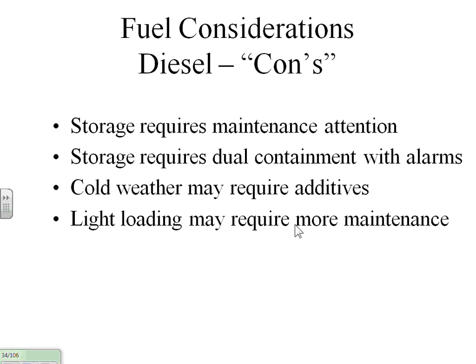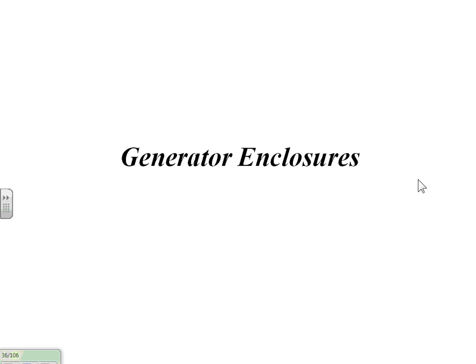Since this was a mountaintop site, they said, what can we do? I said, you need to have a bigger load on this thing. So they didn't have money for a load bank. Load banks can be kind of expensive. So I sold them an electric furnace, and that took care of their problem. An electric furnace is the same as a cheap load bank. So anytime that unit ran, that furnace would also run. We just put it outside. So there's always a way to get around it.